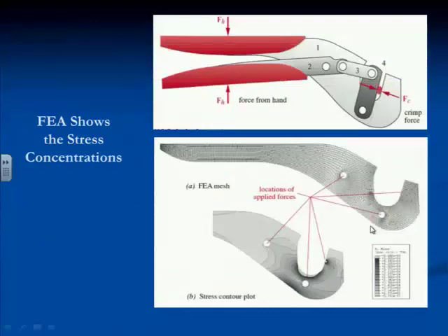This shows a crimping tool, which is used to crimp a little fitting on the end of a wire. You've probably used those things. So it just smushes the fitting onto the wire, and it takes a fair bit of force. This particular one developed 2,000 pounds of force at that crimp. And as such, you get some stress concentrations. If you do a stress analysis of this part, you will see the stress concentration show up in the stress plot,